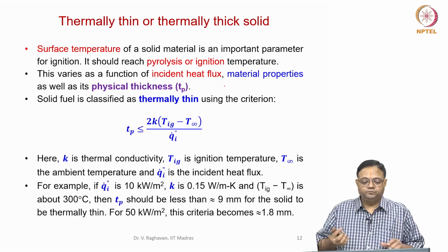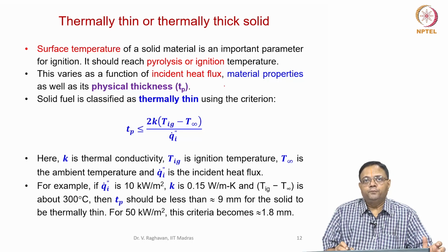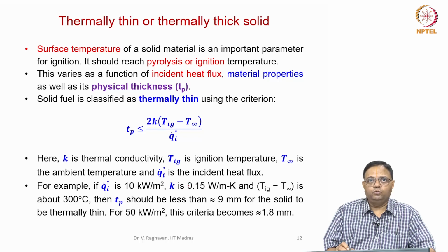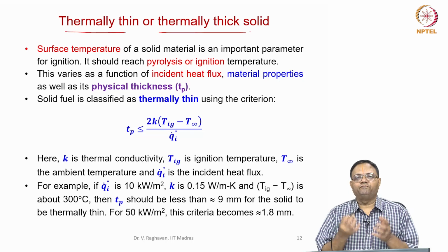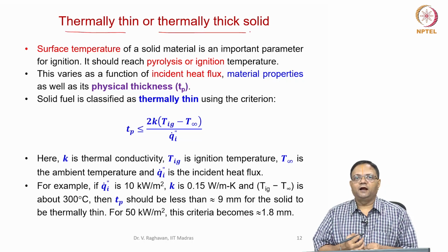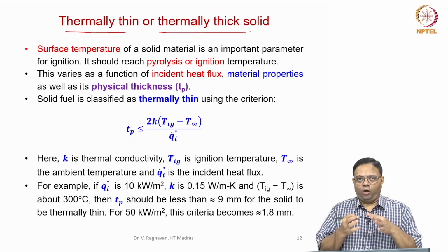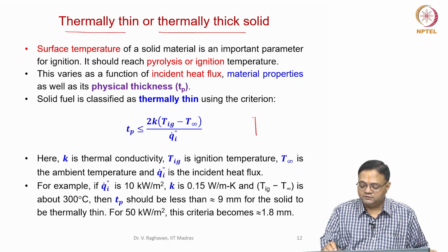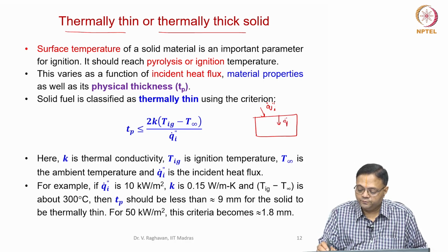Now, in order to understand the ignition in a more clear manner, we have to talk about the effect of conduction heat transfer within the solid, because in all these cases the surface gets the incident heat flux, and the conduction occurs.